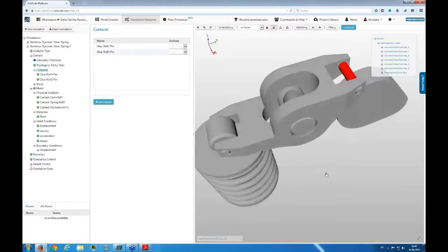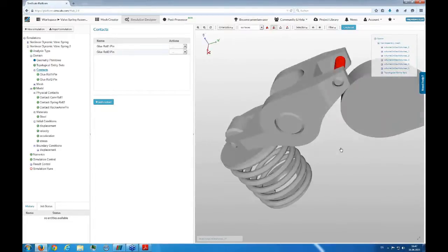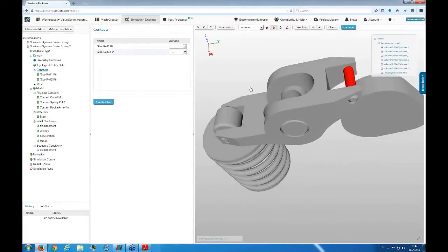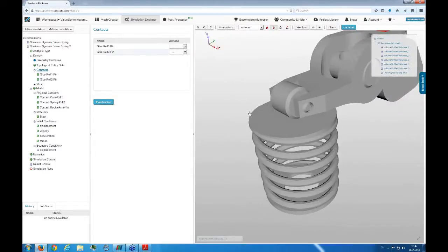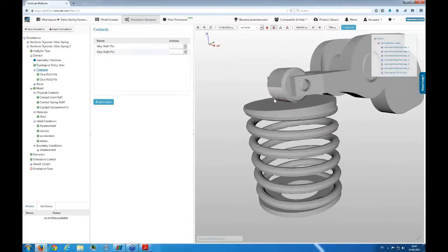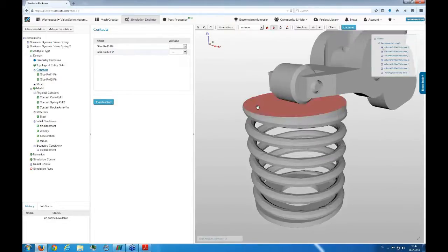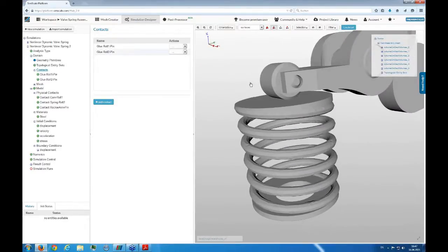And normally, if you have a very good resolution of the contact, you use as the slave surface the surface which has a higher mesh density, so which has more elements over the surface. And if you have, for example, like on this side here, a very curved surface and a very straight surface, then you will always use the curved surface as the slave and the straight one as the master, because there you get the best approximation of the contact of the surface normals.